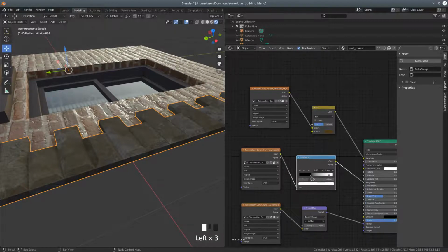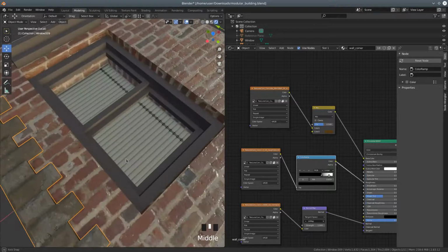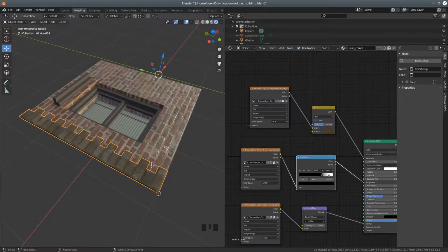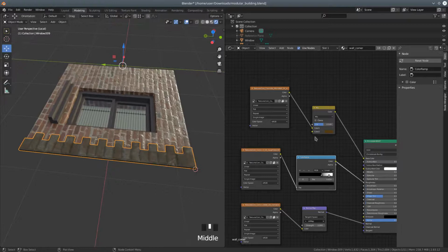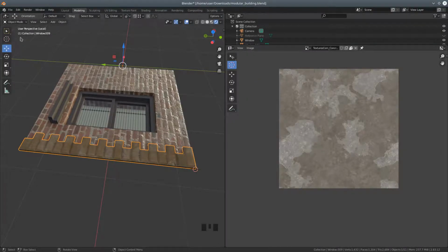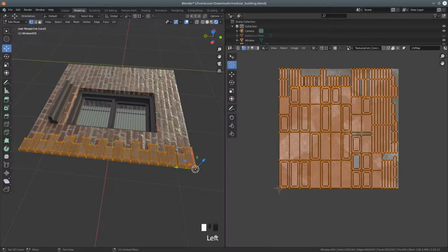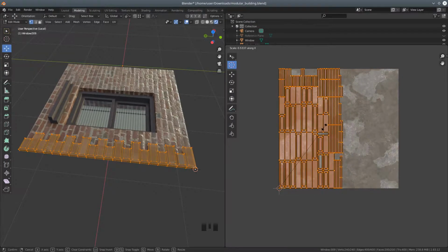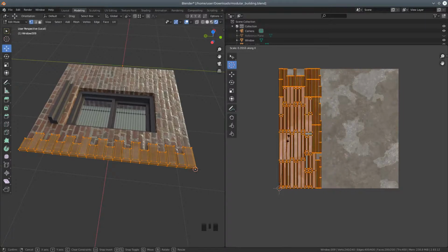I'm really just playing with this now, just to see if I can achieve an effect I like. I'm just wondering if that texture is somewhat too big. So I may go back to the UV editor and go into edit mode. I might just scale it on the X from the 3D cursor, so scale on X. I'm just going to pull that across, because it kind of was halfway across, wasn't it? Just trying to get an idea of what it does to the texture scale.